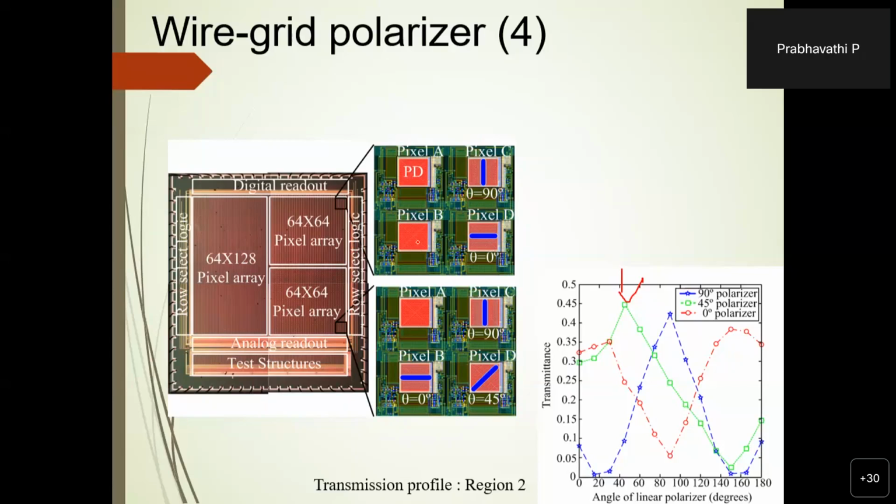In fact, let me make a statement that it is much easier to eliminate the background light in analog processing compared to digital, because in digital you have to read the entire frame to do your subtraction. If you have a 1 megapixel imager, then you're reading a 1 megapixel image to take out your background light, right? We have our work published in TCAS 1, I think in 2019-20, wherein with a single capacitor in the pixel, we were able to reduce 120 kilolux of background light. So that is much easier to do in the analog domain compared to digital. Okay, I got it, sir.